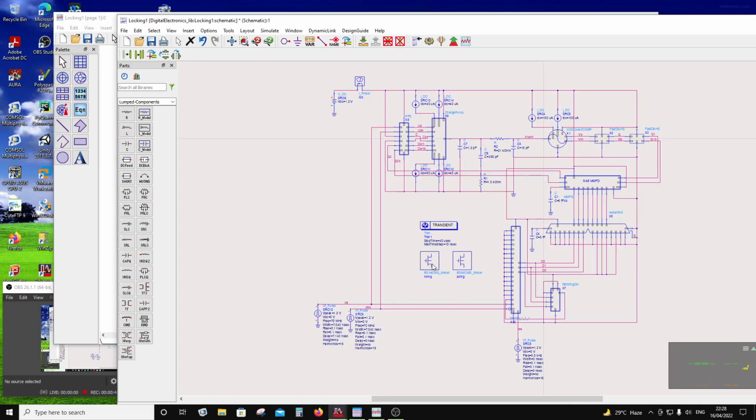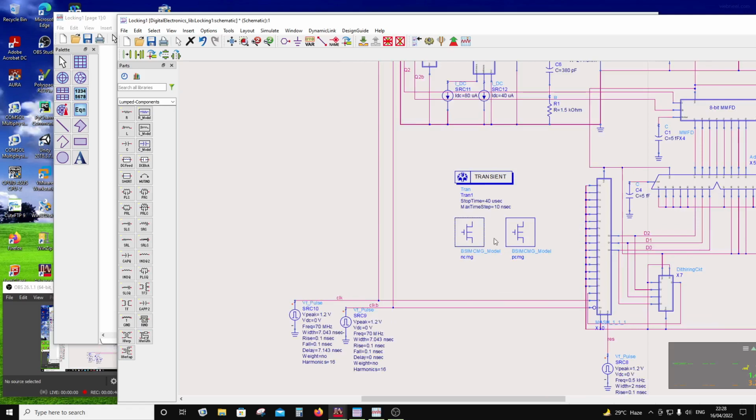As far as the PDK is concerned, these are BSIM CMG models, which are fitted by me for your NMOS and PMOS devices. They are scalable models which I have fitted, and they have process skew also modeled into them. The way I did this modeling was, initially I did a simulation in COMSOL, a physics-based simulator, and I simulated your fins for different sizes.